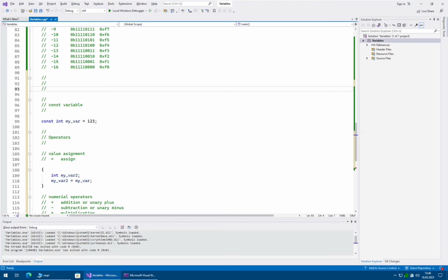And an important thing to know at this point is that all the floating point operations you can in principle emulate using integer arithmetic. So you can, if you wouldn't have a floating point unit in your CPU, something which of course for modern desktop CPUs would be absolutely unthinkable, but something that on a very small system on a chip or a microcontroller like an Arduino might in fact be the case.